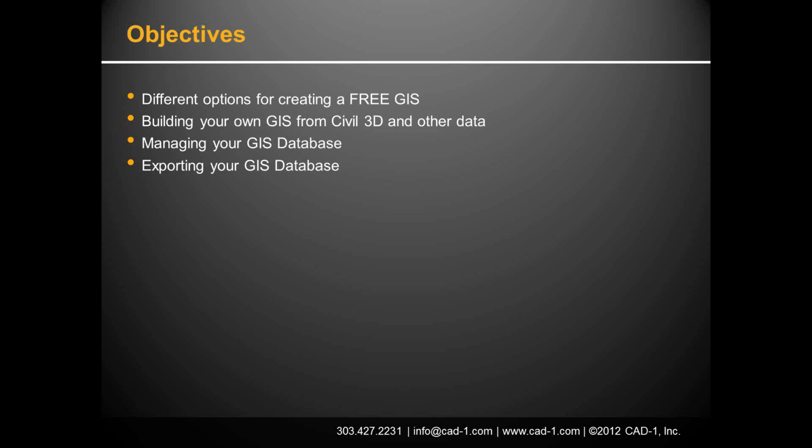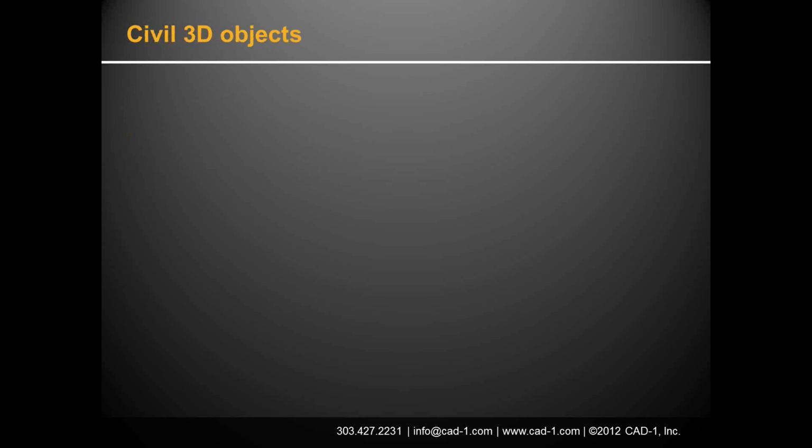Exporting your GIS database, because everybody else is going to want to share your data. You're going to start building up something for project use, and then somebody, a city or county agency or your best friend's mom, is going to say, hey, I really like this, so why don't you send it to me as a shapefile? So I'll show you the quick workaround on how to do that.